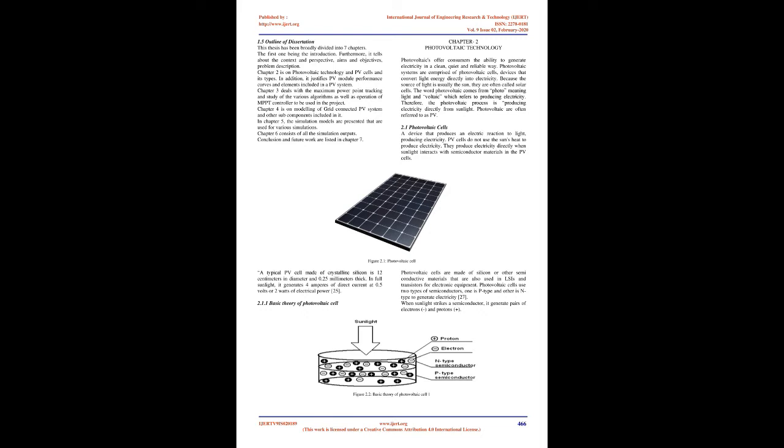Wang Jianqiang and Li Jingzhen [8] researched two grid-connected photovoltaic power systems. One is 10 kilowatts located in Beijing, the other is 100 kilowatts located in north of Shanxi province of China. Inverter and its different modes of operation for both the photovoltaic power systems were discussed. For the 10 kilowatt photovoltaic power system, single-phase transformerless grid-connecting inverters are applied to the system. The inverters have two-stage structure, DC-DC and DC-AC, but they often operate only with the last DC-AC stage according to the panel string output voltage. For the 100 kilowatt photovoltaic power system, three-phase transformerless grid-connecting inverters are used.